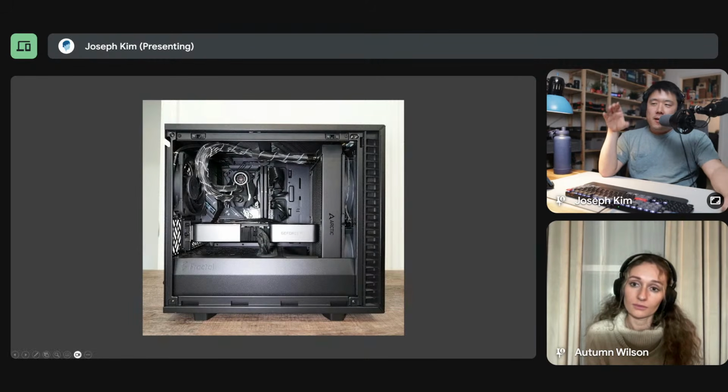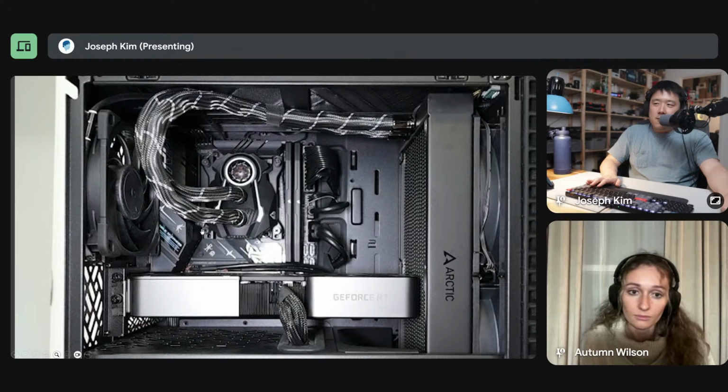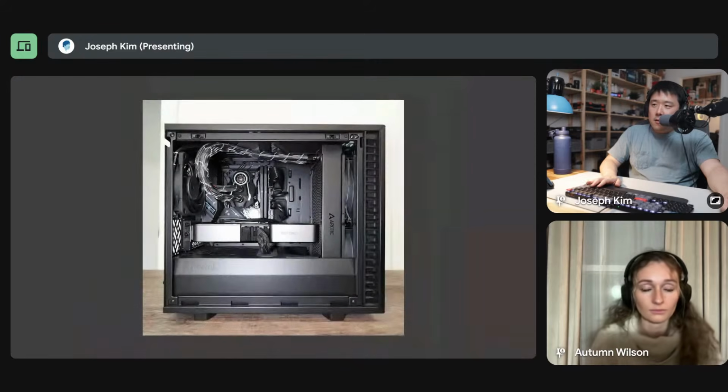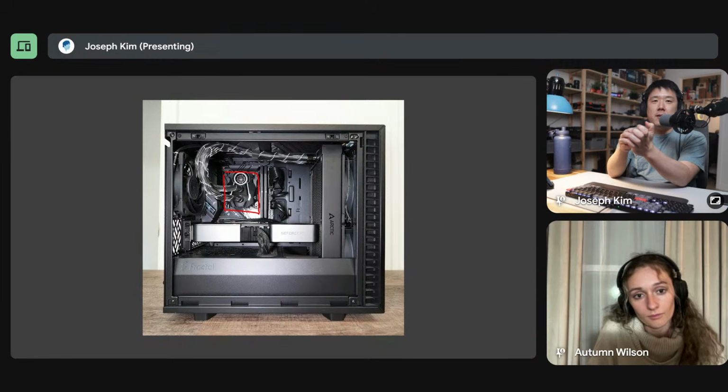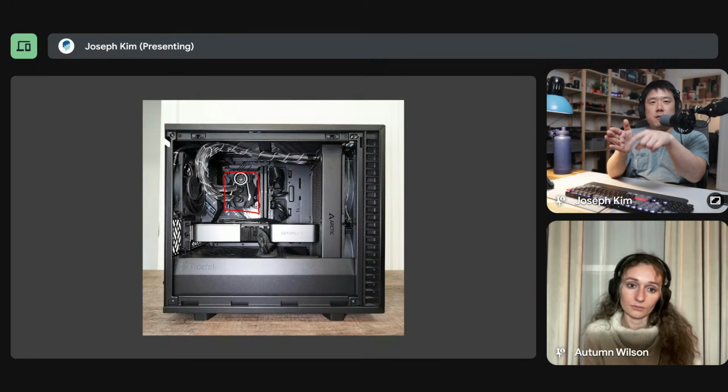at the top of the motherboard is all the pins where you put the CPU, a very delicate chip. And then you put this cooling block, which looks kind of like this thing over here. Can I draw on this? Yes, I can. This thing is a CPU block, and at the bottom of it is a metal plate. Inside of that metal plate, in this black plastic, is basically a water chamber. The water never goes out of it, but the bottom of it is metal. Therefore, it makes contact with the metal top of a CPU.